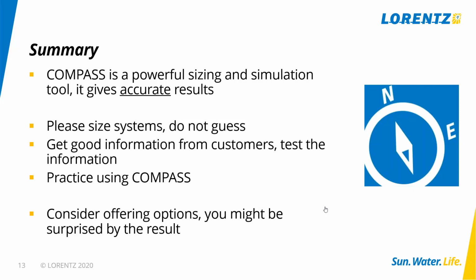Use it, try some scenarios, do lots of what ifs. So say, okay, what if I increase the pipeline? What if I want to use a different wire size? What if the customer wants more water next year? What if the calculation of head, I don't really trust this guy, he's not very good at measuring. What happens if it's 20 meters wrong? So you can test all these things using Compass and come up with different solutions.